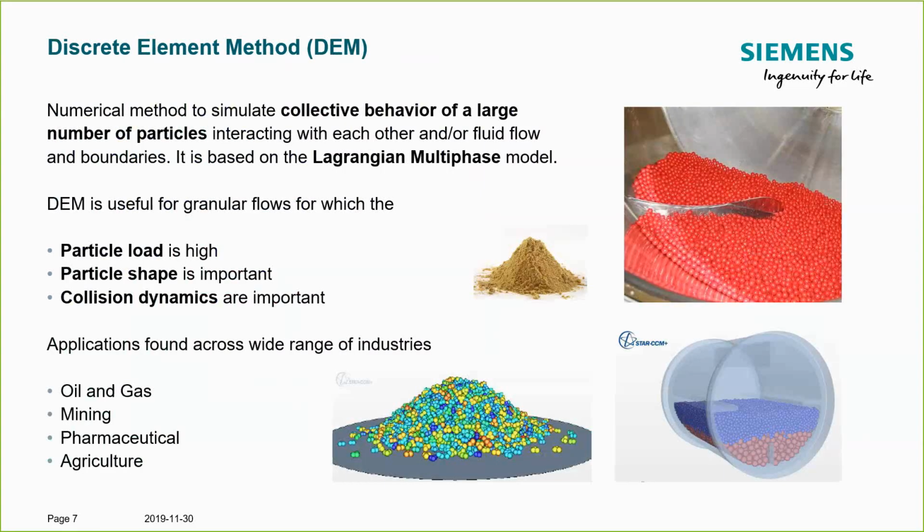Now, how do we, as a naval architect who is familiar with running resistance tests with StarCCM+, account for this additional physical problem? So StarCCM+ comes with the discrete element method, which is a numerical method to simulate the collective behavior of a large number of particles interacting with each other and/or fluid flow in the boundaries. And this model is based on the Lagrangian multiphase model as a meter-level model, if you recall the physics continua tree that we have in StarCCM+.